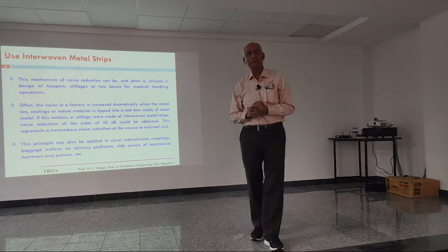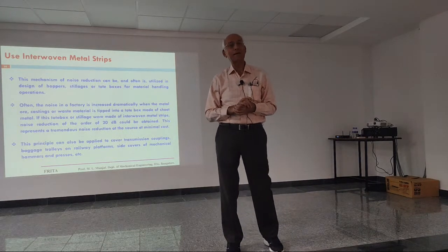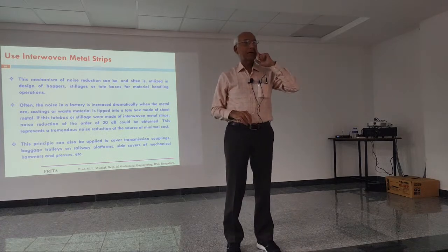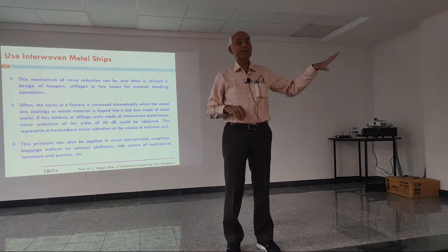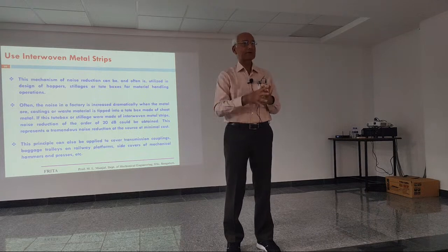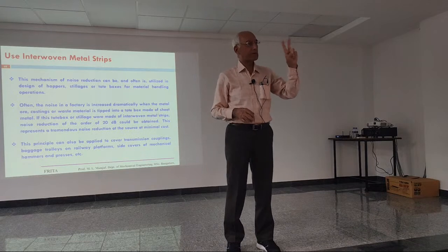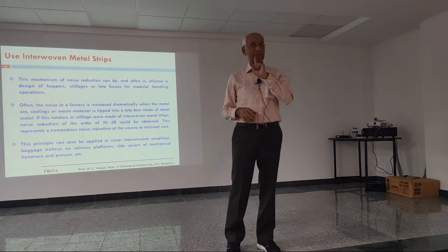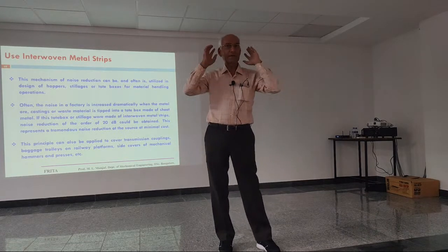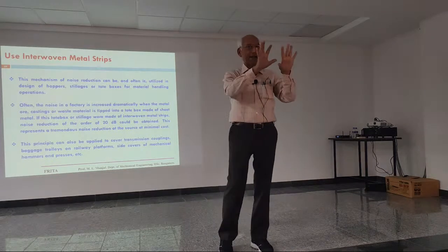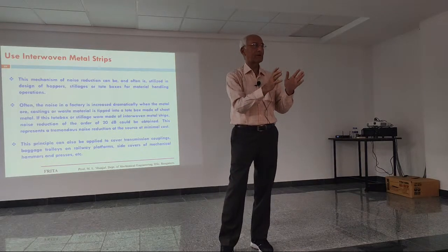And another thing I'll tell you, the practical side, you may laugh at the whole thing. Those days I didn't have a sound level meter which immediately within 1 second gives me a spectrum. I had the old fashioned one. It used to take me 45 minutes on one spectrum. So if I'm taking readings, I had to stand there for 45 minutes to complete one frequency spectrum.